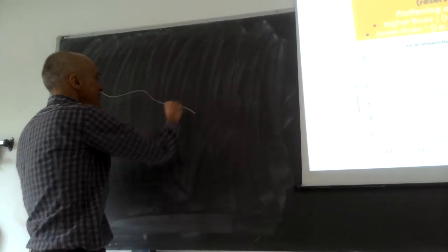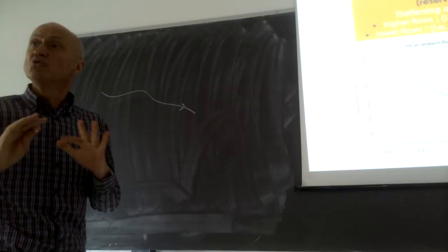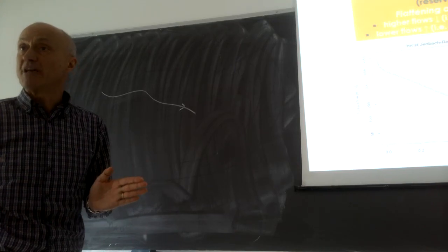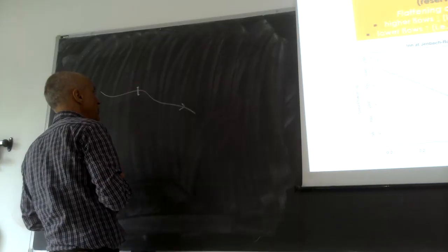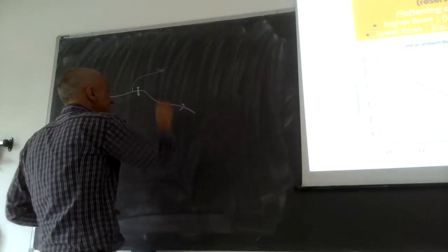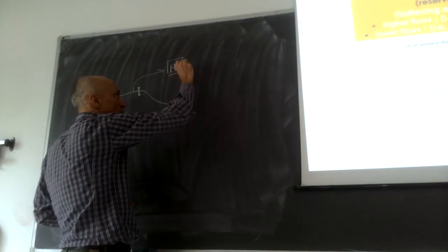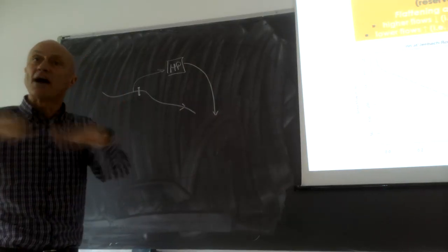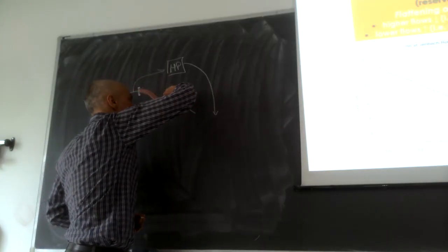So with the barrage, part of the river discharge is diverted, sent to a hydropower plant producing hydropower electricity, and then returned to the river only downstream. Okay? So you have a segment of the river now that sees less water. This produces an impact as indicated in this diagram. So the whole flow duration curve is lowered.